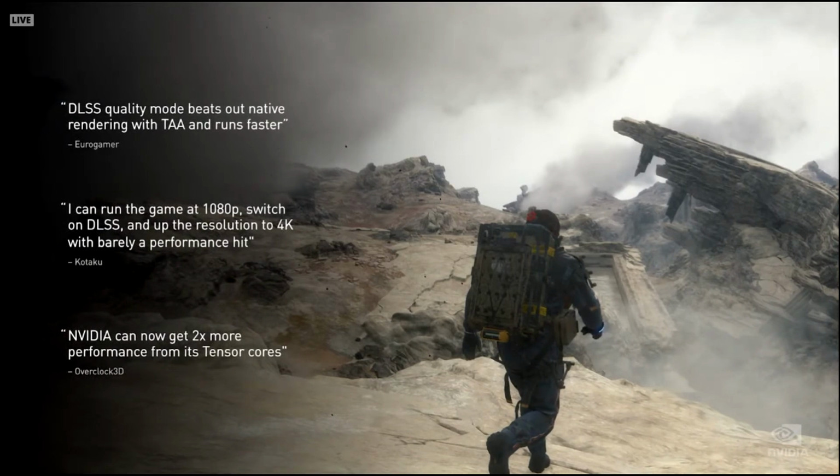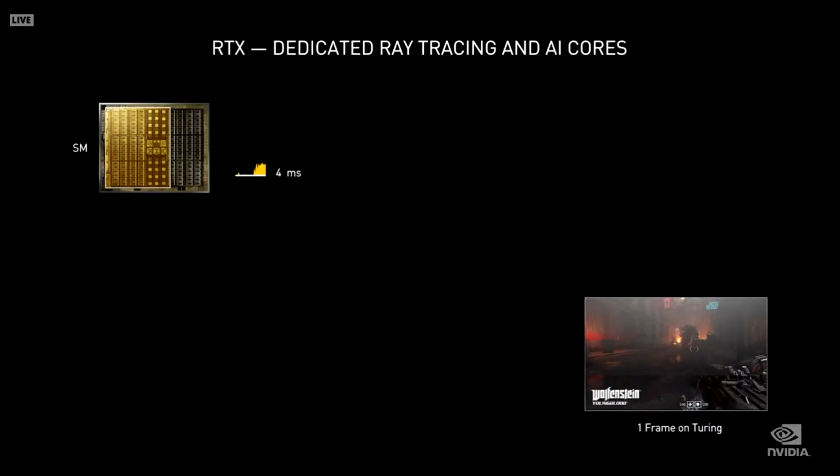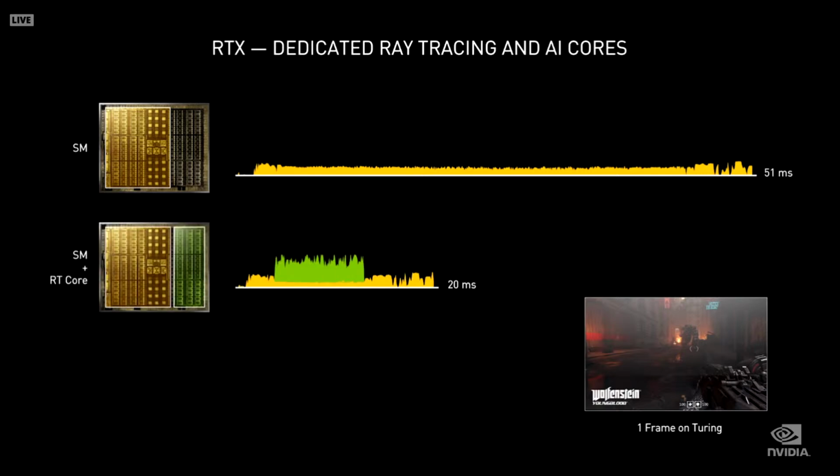Let's look at one frame trace of a game to see the processors of RTX in action. Adding ray tracing to games dramatically increases the computation workload. Using shaders to do ray traversal and object intersection reduces the frame rate. We added the RT Core, which reduces shader workload by 60%. RT Core offloads the shaders by doing the ray triangle and ray bounding box intersection calculations. Using the same methodology as Microsoft Xbox, the RT Core is effectively a 34 teraflop shader, and Turing has an equivalent of 45 teraflops while ray tracing.